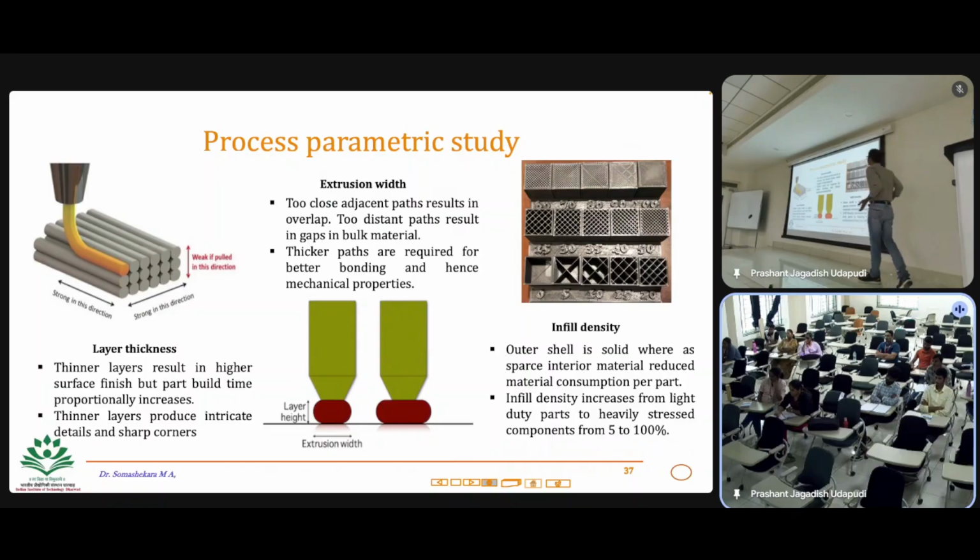Uniformly you can add the material, so that you don't need to worry about variation in the properties within the printed component. Imagine I have this material at maybe 20%; I could as well add that 20% towards the left alone. But then when I test something here on the right side, I'll have different properties.